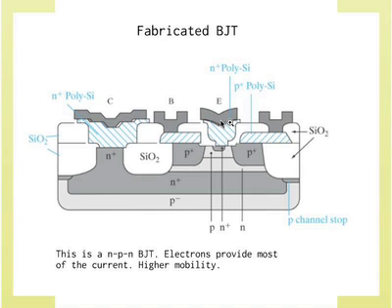So what happens? The emitter base junction is forward biased, so let's look at it. The electrons come in, it's an N-type emitter, so electrons are the majority carriers. They get injected across this junction, and then you have a very thin base region right there. So the electrons come across, they will diffuse quickly across to the base. Sorry, diffuse across to the collector, my mistake, not the base.